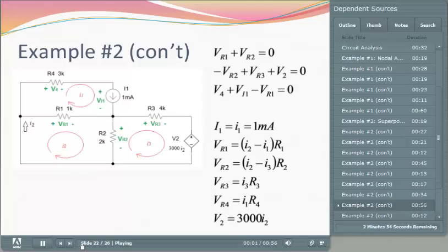I have decided to continue using mesh analysis. There are now 3 meshes in this circuit, and I have labeled the current flowing through the upper mesh I1. I've continued to call the mesh on the lower left I2, and it is still equal to the current leaving V1, which is now a short circuit, and I3 on the lower right mesh.